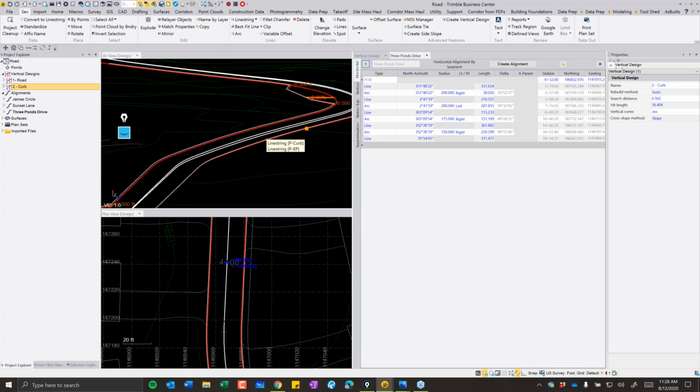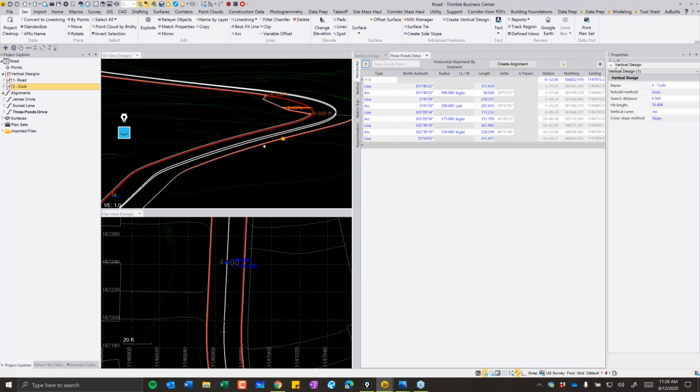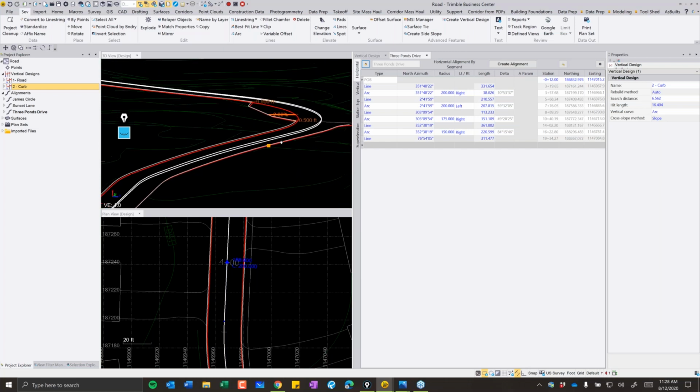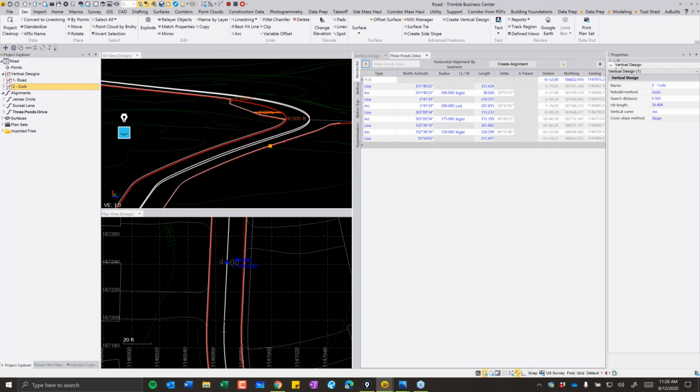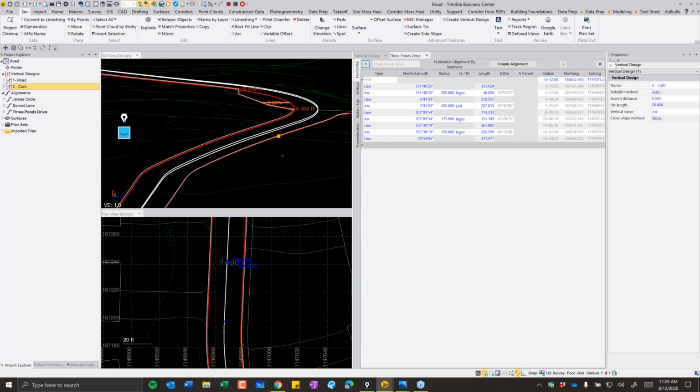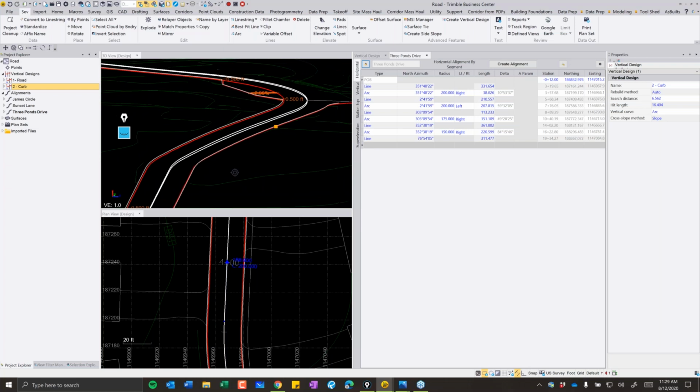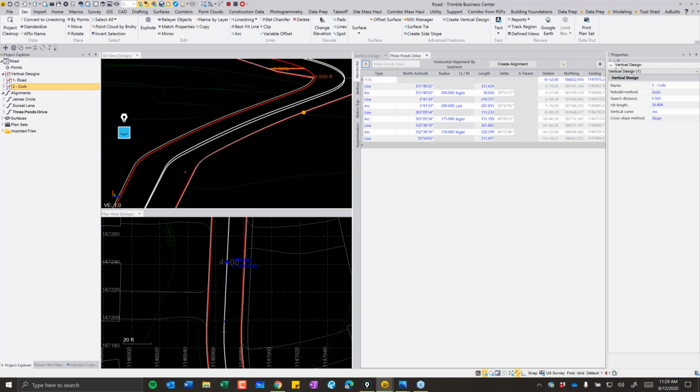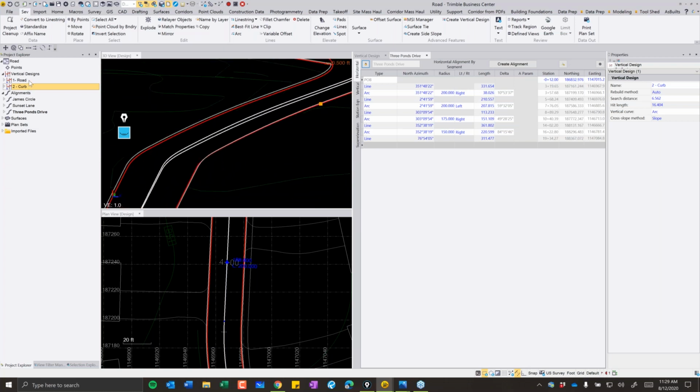Yeah, it's interesting that you build your models in separate vertical designs, but you daisy chain them off each other so that once the first one is updated, the second one automatically updates from the first one, rather than putting all those instructions into one big vertical design. You keep it simple by keeping them in little groups, and then allow the groups to daisy chain one to the next. And that's why you're using that numerical value at the start of each vertical design name to keep them in order, so it's processing them sequentially. That's a good idea. Great.